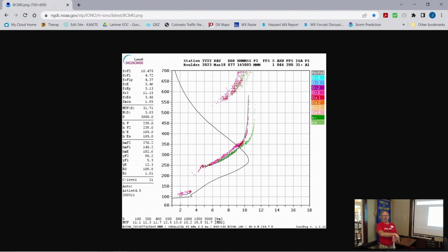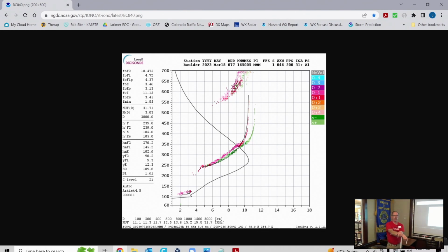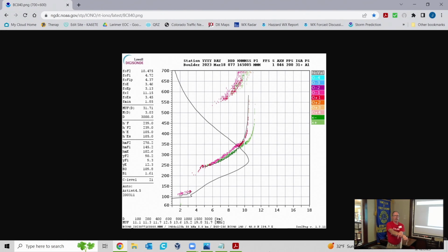And there's an Aries HF net every Sunday morning, 3.8 something, 3810, 8 o'clock in the morning, 80 meters. And their net control's usually in Pueblo, and they have people all over the state. I have gotten out of bed early enough to go up the Poudre Canyon to Stevens Gulch, set up an NVIS antenna, and work their net. And I've always been able to work their net at 8 in the morning every time I've tried.